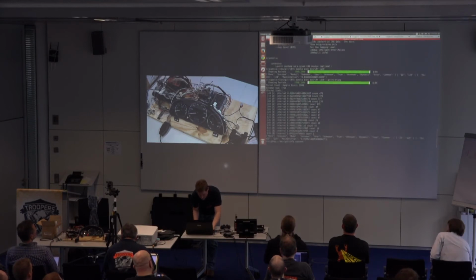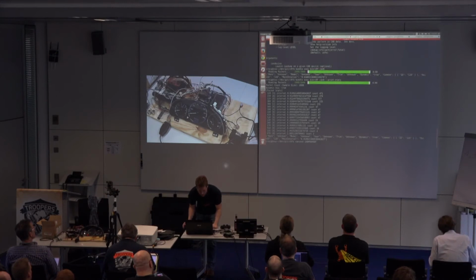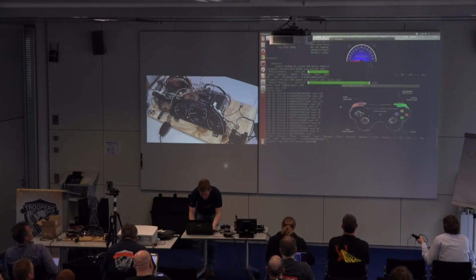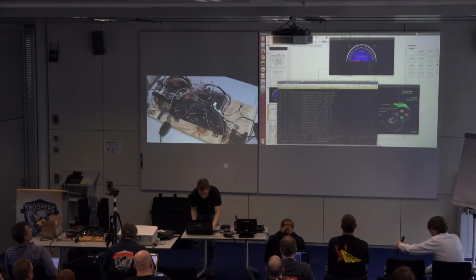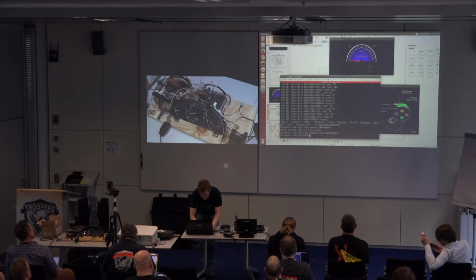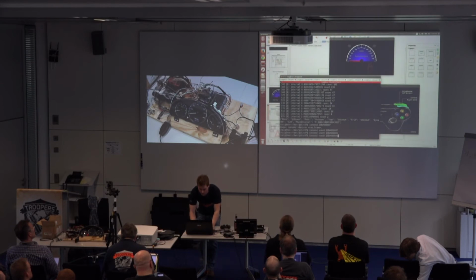cansend. When using cansend, all you have to do is send it the signal ID and then your bytes. Let's see, how am I going to do this easily? I think I need to pull this down. All right, we have to tell it where to send to: vcan0. Nothing moved there, zeros. Okay, so when it's 0, the door's unlocked. When it was F, they were locked.